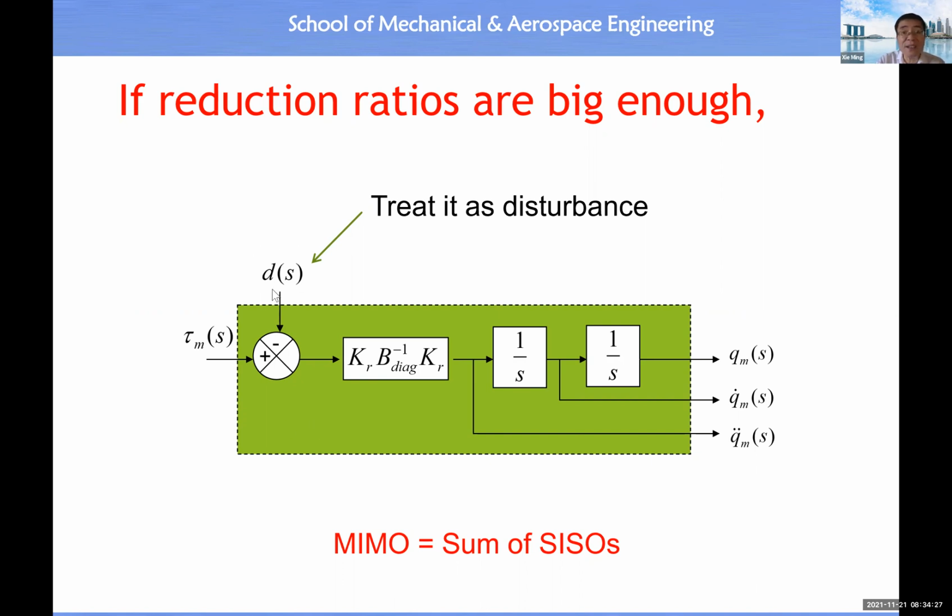Then how do we achieve this result? The answer is, in module 2, when you design your robot body, try to choose a torque joint with a very, very high reduction ratio. This is the only condition for you to consider when you design your robot's mechanical system. Therefore you understand speed reducers are very, very important in industrial robotics, because through a speed reducer with a high reduction ratio, we can make a robotic arm become an LTI system. Then we can apply this property of an LTI system.